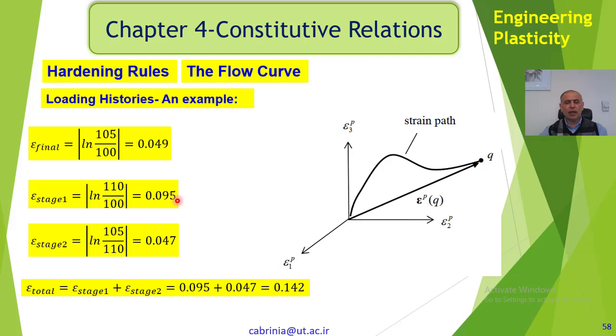That's what happens in real physical forming problems, metal forming problems, for instance, when you form a sheet of metal, or when you forge a component, anything, when you change the shape of the metal, you get this kind of strain. In fact, there are some strain loading histories which cause intermediate strains which we do not see. So if we just take the initial and final stages, we don't get the right answer.